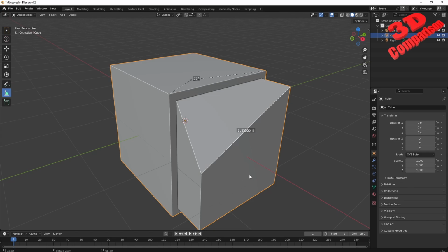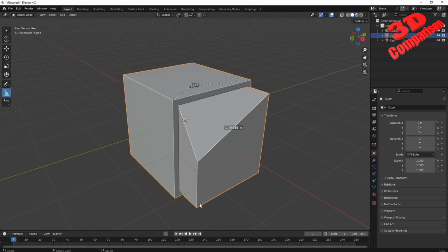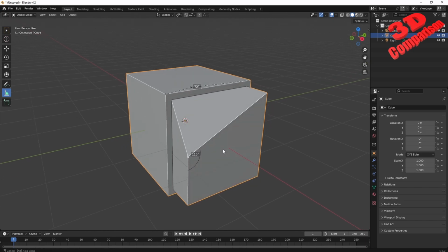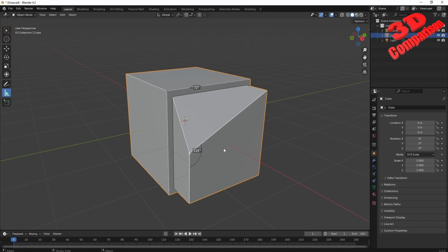For example, I have this edge over here, but I want to measure this angle. Therefore, I will not do another measurement over here. I will just resize this in order to have the angle, have this snapped over there and this over here. And we're going to see an angle of 150 degrees over here.